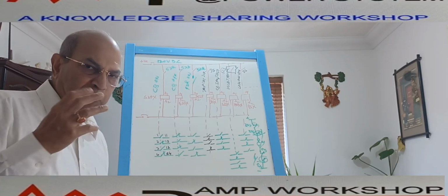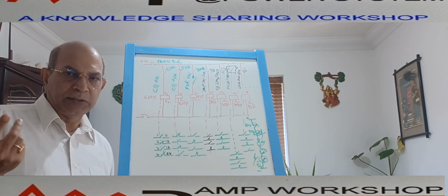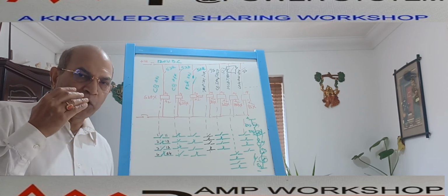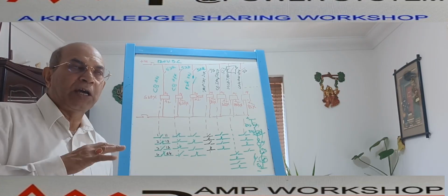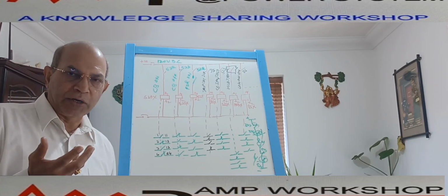Similarly, suppose the spring charge mechanism, when the spring is charged, has 1 NO or 2 NO 2 NC contacts. Now if we want to monitor the spring charge condition from the switchgear panel as well as various remote locations, how can we do that? We don't have any more contacts.